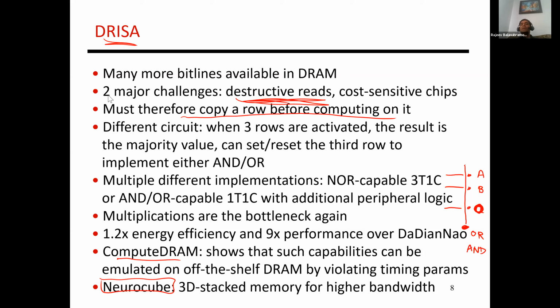And so what are the drawbacks of in-memory computation, and is it not mature enough yet? That's, I would say, one of the key issues so far. The compute cache paper appeared only in 2017, and so I don't think that circuit has been around long enough for it to find its way into commercial products.